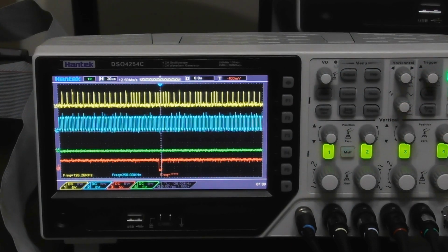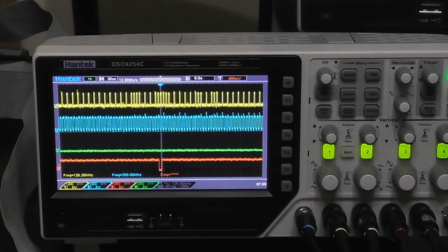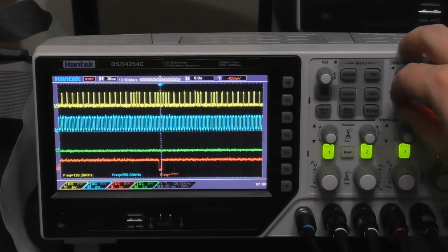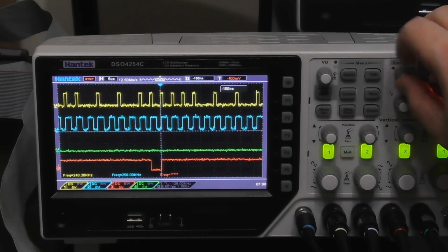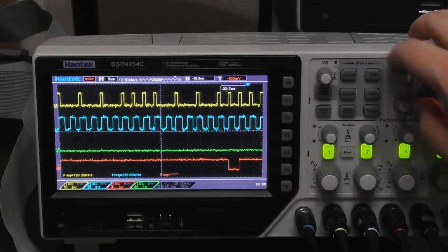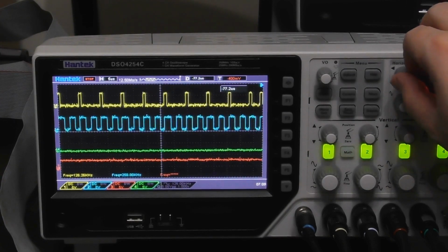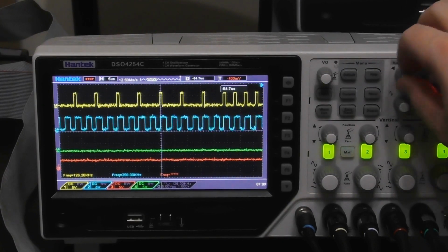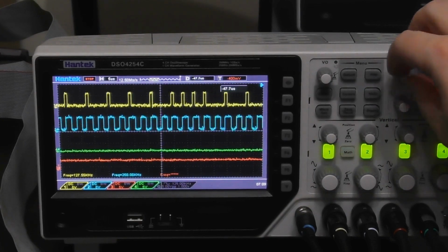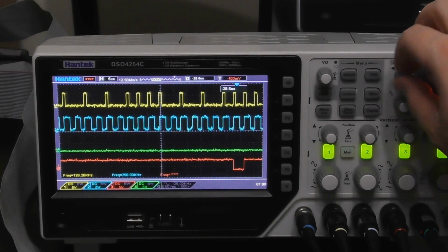So if I zoom out a bit now, what I'm hoping to see, if I take a single frame snapshot here, is one of those address mark bytes. So let's have a look at the yellow trace now. Going to zoom in again. And remember that the sequence that gets stored on the disk is a very long sequence of zeros, which we have over here, followed by a byte with the clock pattern of C7.